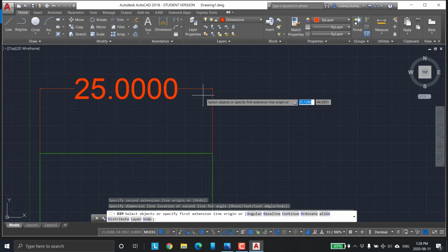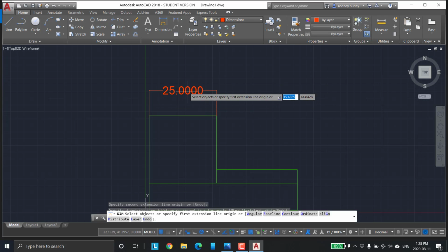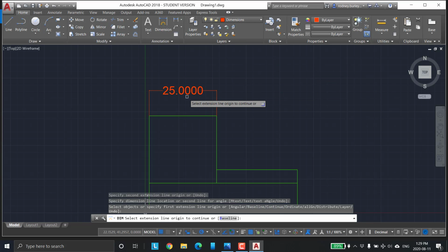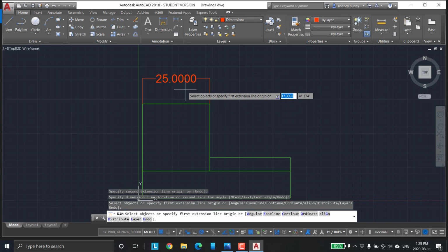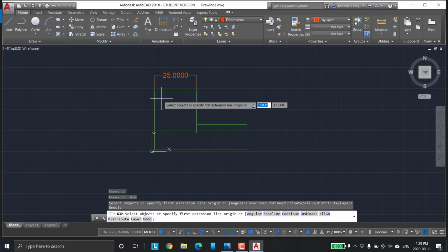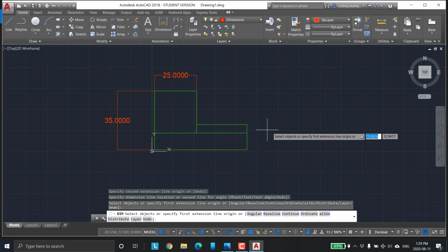And you can change other things too. You notice the arrowheads are really small. I can go in and modify the arrowhead sizes. I can also, you see how it's got 3, I can change that as well. Within the same thing, going into the standard text and modifying the arrow sizes and the precision of it. I typically only go 2. Well, we'll go over that a little bit later, but 2 decimal places or 3 decimal places at most. So anyways, that's not what this is about. I want to show you this. So now we measure this height here to here, and you can see that's 35.